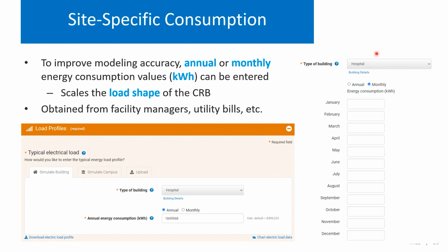Sorry to interrupt. Yeah, each building also has a separate non-electric heating profile associated with it. And if you click on any of the thermal technologies, you will see that the commercial reference building also includes non-electric loads associated with these reference buildings. So we're just looking at electric loads for now, and that includes electric heating, electric HVAC and electric water heaters, but there are non-electric thermal loads that are also associated with these reference buildings that can be modeled based on the housing stock for each of these climate zones. Okay, thanks guys. Yeah, so REopt does model both electric and thermal loads, and depending on the interest of the analysis, could explore options with different technologies.